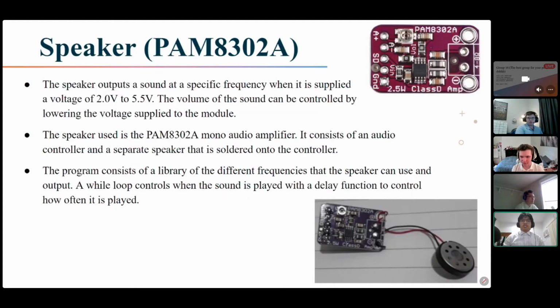The sound component that is used for our project is the PAM8302A with a speaker that is separate from the board that you would need to manually solder. This component is able to play a wide range of frequencies, so we are able to make it play any sound that suits the project's needs. For this project, we decided to use it as a sound alarm. So if we were to make a final prototype, we would replace this component with a simple alarm or buzzer. This is because the price for this component is quite large.